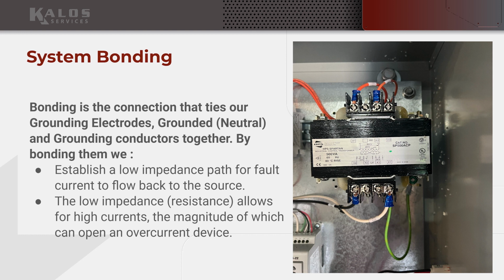and we will have serious electrocution hazards present in our buildings. So if you are installing transformers of any size, anything over maybe a little 50 VA transformer, you need to start thinking about bonding. And if you don't have a firm grasp on this, I'd like you to try to set up a meeting with me, and we could spend more time really nailing this down to understand these concepts. But just always be thinking about this when you're installing transformers. Am I bonded? How do I bond? We want to make sure that this happens with every transformer we install.